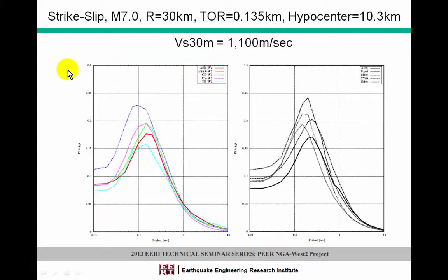If we finally go to what would be more typical of a site-specific VS30 value for Diablo Canyon, you can see these are the two comparison plots. We're starting to see an even bigger spread in the predicted motions, especially at the intermediate and high frequency range. But again, at the longer periods, you're still maintaining that tight clustering or agreement between the models. And again, as I mentioned before, the Campbell-Bozorgnia model is showing this shift in the peak as we get to a higher shear wave velocity.